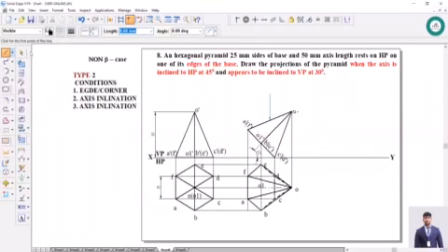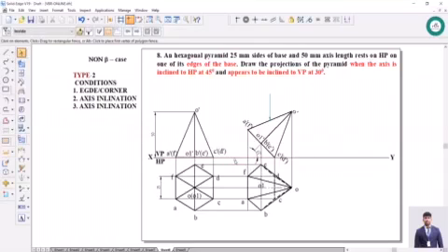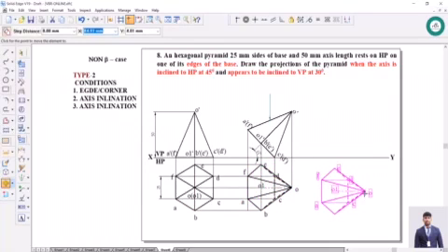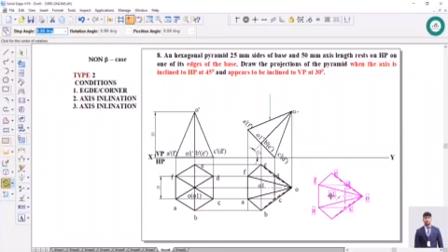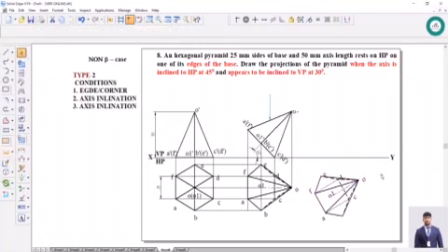So further, to satisfy the third condition, select this particular, go to move, and one reference point you can place it. Immediately go to rotation option. You are rotating with respect to horizontal, that is O1O. Click this and directly enter the given value, that is 30 degrees. So you can rotate this way or this way. I will be rotating this particular way so that the apex is nearer to this.